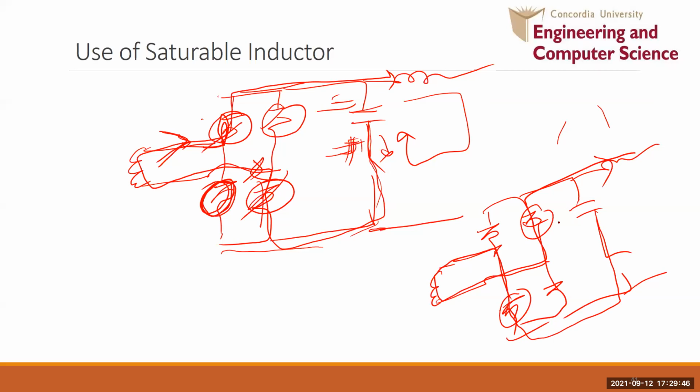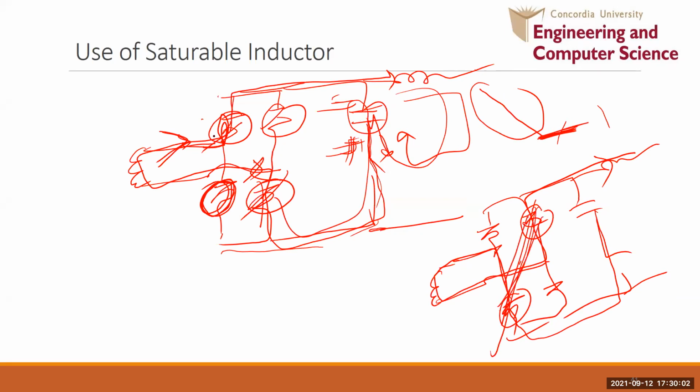So initially this capacitor, when the transformer is changing direction, will store this energy, and when it is steady state, it will transfer back through the particular diode pair which is conducting. During negative this one, and during positive, again it will store energy, and when it is positive, through this one it is circulated back to the output.